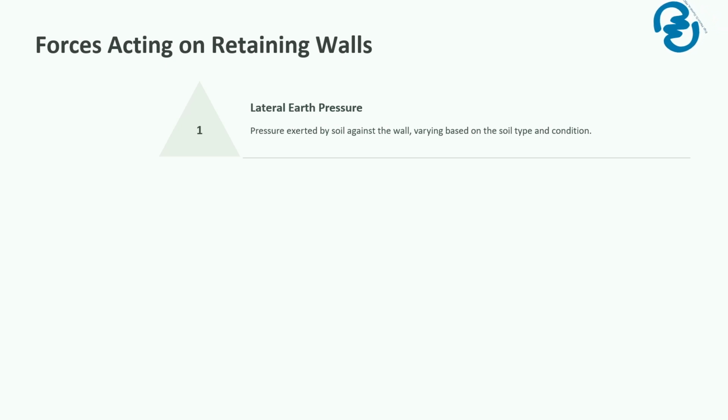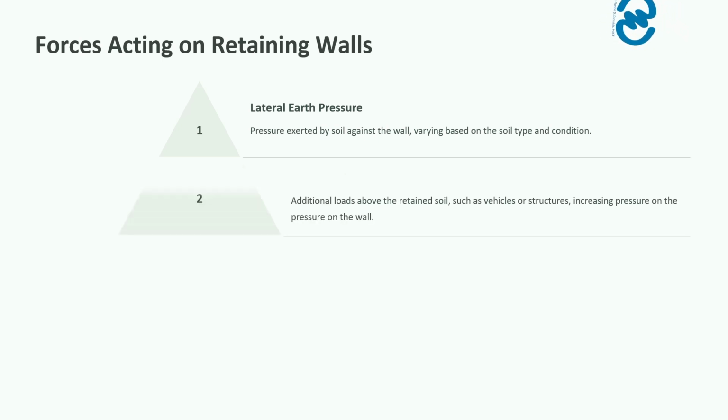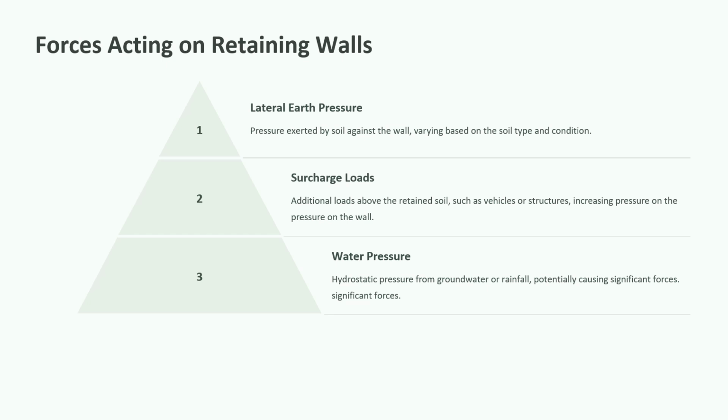In addition to earth pressure, retaining walls often experience surcharge loads, which are additional forces from structures or vehicles located near the wall. Water pressure is another critical factor, especially in poorly drained soils, where water can accumulate behind the wall and exert significant force. In regions prone to earthquakes, seismic forces must also be considered, adding further complexity to the design process.